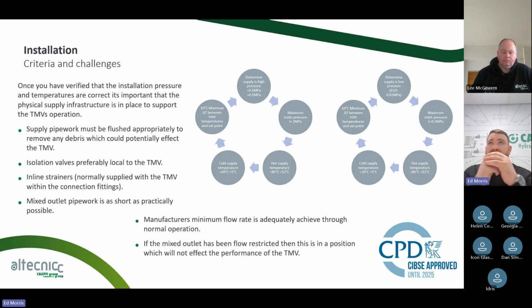And then there's a little circle there: are you using high pressure, are you using low pressure? Have you got the right supply temperatures? Have you got the right supply pressures? Is it a balanced valve? Do you need equal balance from the hot and cold coming in? Can it work with an imbalance?